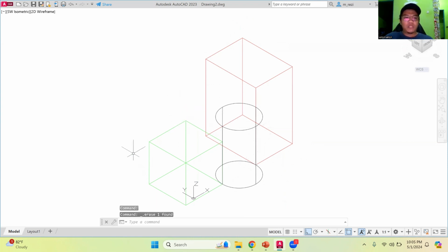After that, I will create a cone. Maybe I will place it somewhere in here, 100 millimeters away from the cubes. It doesn't really matter where. This point introduces you to the concept of primitives, basic 3D objects. It's a primitive object, a simple solid.